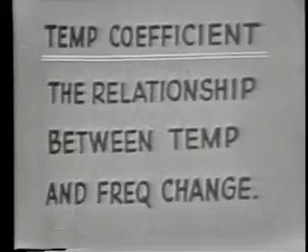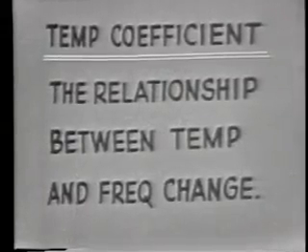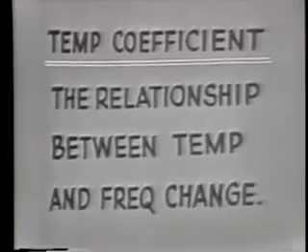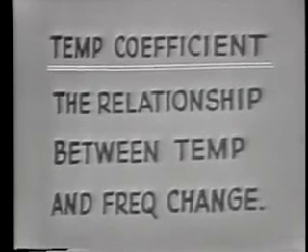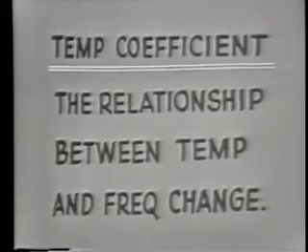Now, another characteristic which will be different for the various crystal cuts is the temperature coefficient of the crystal. The temperature coefficient. Now, this is a new term, so let's define it. Temperature coefficient is the relationship between temperature and frequency change. Then at this time, complete item 6 in your TVI guide.